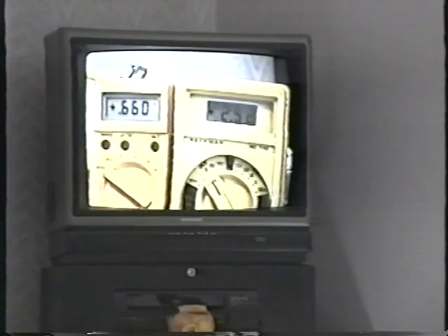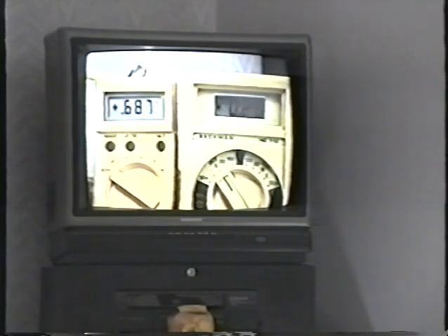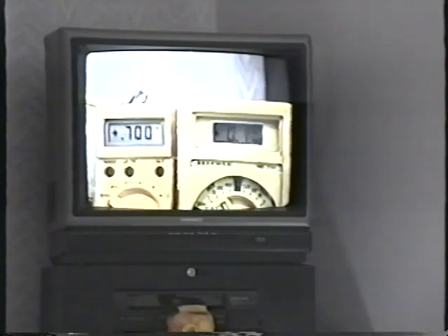Let's see if I can turn this back on now. There we go. So here we go again. And watch what happens now. As I increase that base voltage just a little bit, that collector voltage drops like a rock. I mean, the base voltage is only moving up by thousandths at a time, and look at the collector voltage drop like a rock until it can never go all the way down to 0. There's always a tiny amount of voltage left. In this case, about 0.16 of a volt.